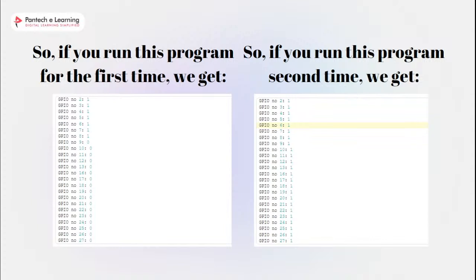Also note that if you only plan to use GPIOs as input, you don't need to call GPIO.cleanup every time. This function is only useful when you have GPIO set as output mode. Another thing is that if you have set your GPIOs to output mode and then to input, chances are that you are going to read 1 for all GPIOs. As you can see here, the default state is only after you boot your Pi. Under a certain set of circumstances, it's quite probable that this default state will be modified in your future programs, right?